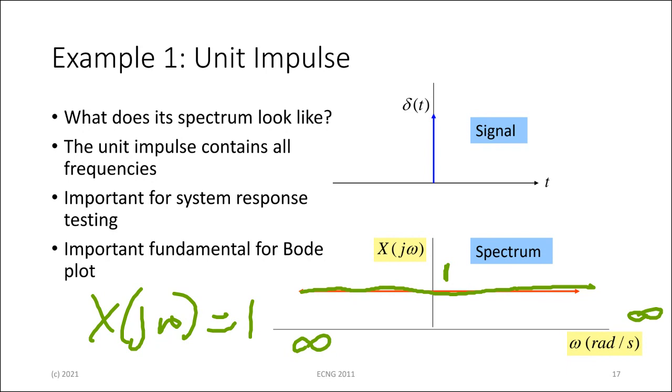And this is why I mentioned that we'll meet it further when we do the Fourier transform. So this is what happens when you put an impulse into a system, or something fairly close, and we'll talk about that in the little example coming up. What you are doing is the equivalent of injecting a varying frequency going from 0 hertz to incredibly high frequencies.